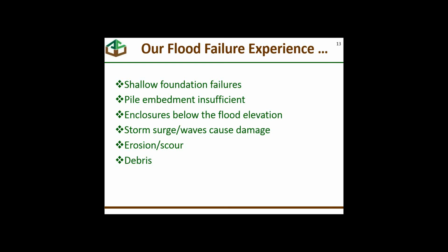See lots of cases where pile embedment is not sufficient. So people typically around the Gulf and Atlantic coasts in many places use pile design parameters, if you will, that have been used for years and years. And that most likely means pile driving equipment that's been used in a business for a long time, driving piles to some arbitrary embedment depth because whoever's doing it has not apparently seen failures.